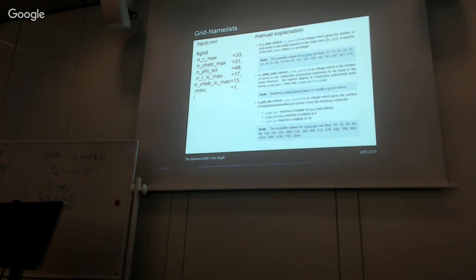So you only solve half of the sphere, and then you say the other half is just mirror symmetric with respect to the azimuth, right? And then, for example, if you say minc is 4, then you just solve the quarter, and then you assume the given symmetry, right? So that's how you can save computational time. You may ask the question, does it make sense? So is it a good representation of my solution?